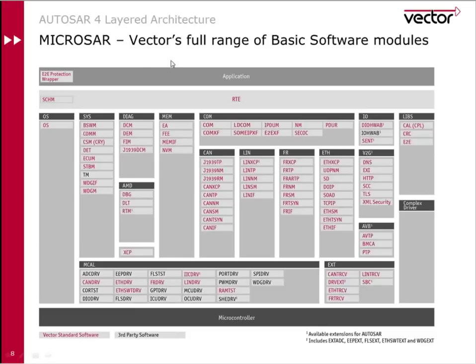Within AUTOSAR 4, the Schedule Manager has moved out from the sys layer in here into the RTE layer, because the Schedule Manager is responsible for generating the task ticks into the application, so the application can schedule its tasks. And so this is part of the software that's also automatically generated in conjunction with the RTE.